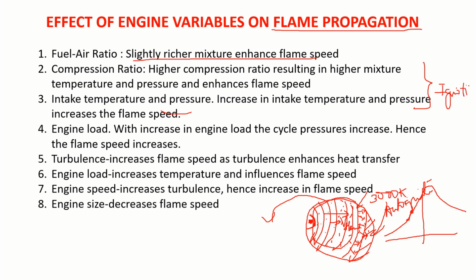That is a problem. If you have more engine load, with an increase in engine load the cycle pressure increases, hence the flame speed increases. Turbulence increases flame speed. Engine load increases, engine speed increases, engine size may decrease the flame speed. So this is the problem. If you want to increase the flame speed, that may even somewhat make auto ignition happen. So this is where exactly the difficulty is.